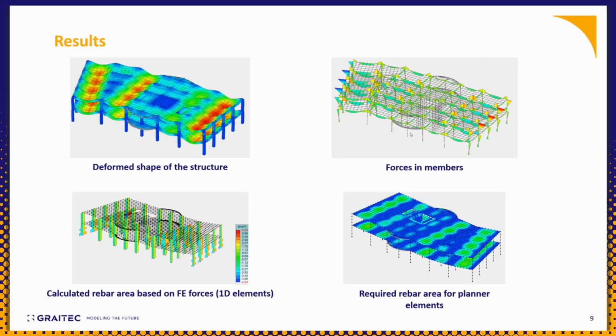So some of the results here. So it's again fully rendered graphics. So this is the deformed shape of this structure. Can check the internal forces as you see there, rebar areas based on concrete design code, and as well you can have the rebar areas in your planar elements like floors or slabs as you see there.